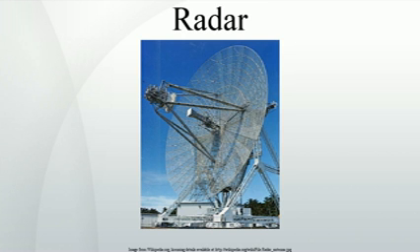Parabolic reflector. More modern systems use a steerable parabolic dish to create a tight broadcast beam, typically using the same dish as the receiver. Such systems often combine two radar frequencies in the same antenna in order to allow automatic steering, or radar lock. Parabolic reflectors can be either symmetric parabolas or spoiled parabolas. Symmetric parabolic antennas produce a narrow pencil beam in both the X and Y dimensions and consequently have a higher gain. The NEXRAD pulse-Doppler radar uses a symmetric antenna to perform detailed volumetric scans of the atmosphere.